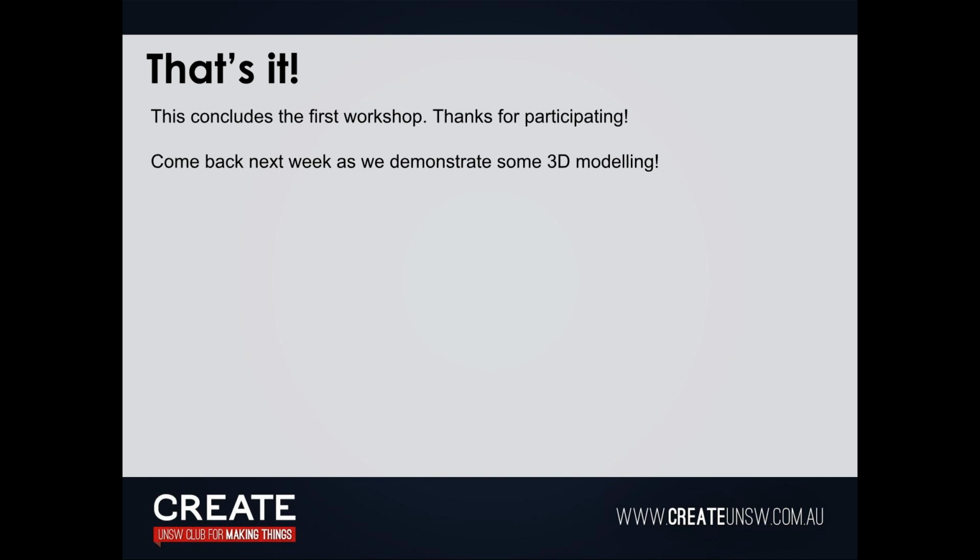If you want to join that, you'll probably have pins in there. So I'm just going to edit that surface. Now you probably can't see that clearly, right? So we go line. Actually, no, we don't even need to do that. That's roughly center. You can find the center when you're actually doing this. Hit circle, that's center. Let's say we put a 2 millimeter pin in there. Hit that.